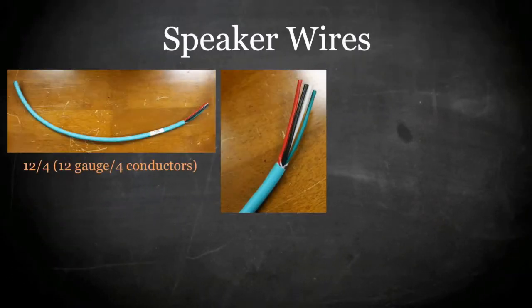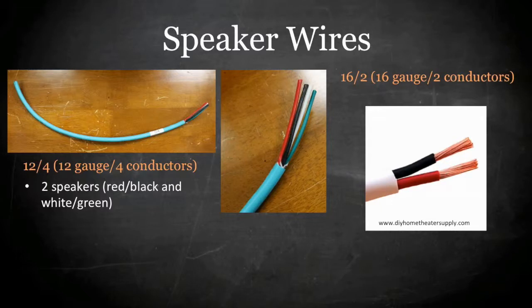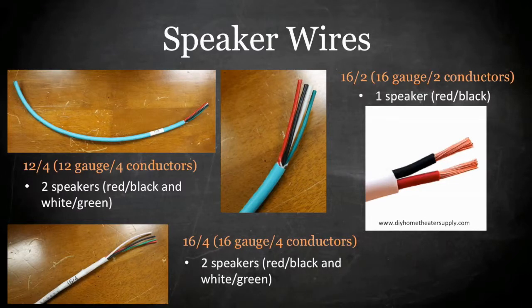12-4 wire can connect 2 speakers using the red-black for one and the white-green for the other. A 16-2 wire can only connect 1 speaker using the red-black wires. A 16-4 wire can connect 2 speakers using the red-black for one speaker and the white-green for the other.